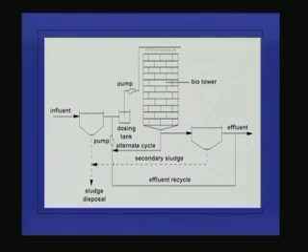So this shows a biotower. Here we can see the influent is coming and this is the primary clarifier. Here all the suspended solids from the wastewater are being removed, and the wastewater coming from the primary sedimentation clarifier is pumped to the biotower, and this is the biotower.